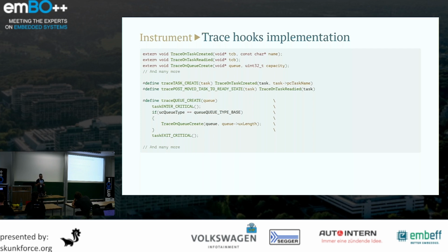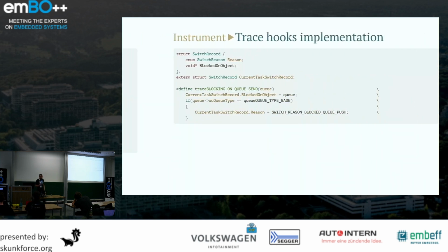The simplest solution is to put the critical section inside this trace hook function. It will slow down the operation a bit. It may shift timing inside FreeRTOS a bit, but this is the case with all kinds of instrumentation. So it's important to be aware of this issue and solve it as necessary.